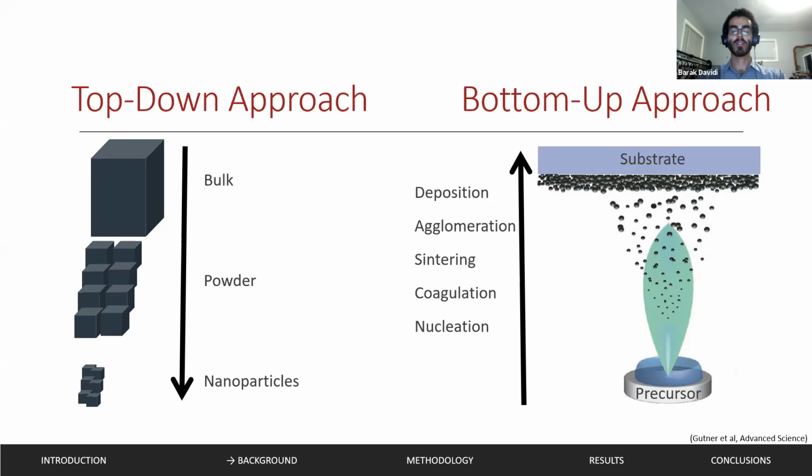In vapor-fed aerosol flame synthesis, volatile precursors are combusted. Particles are formed after precursor conversion by nucleation from the gas phase and grow by surface reaction, coagulation, and subsequent coalescence into larger particles which deposit on the substrate.